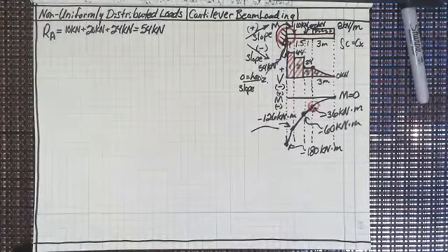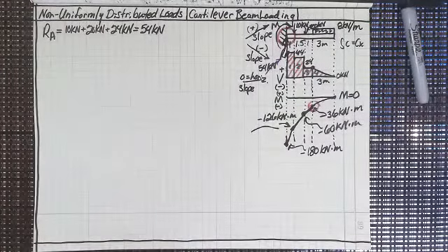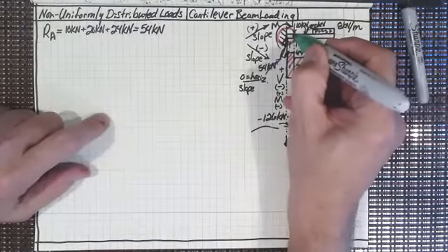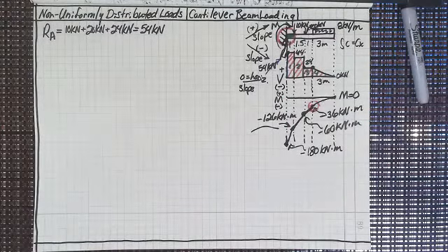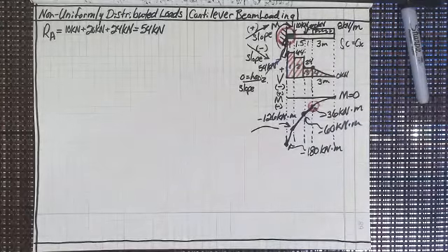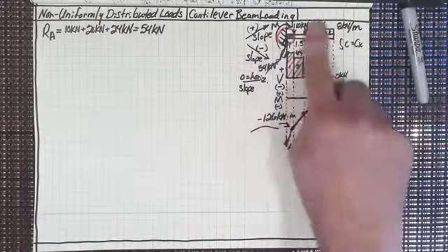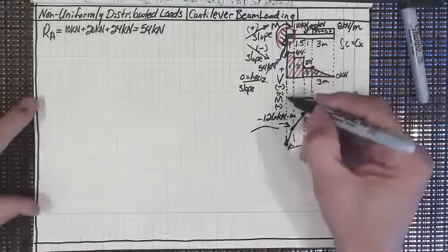Where is the most torque being placed? It's being placed right there where it's hitched into the wall or whatever. And where, let me get the green pen, is the greatest shear stress? The greatest shear stress is right here within that first thing too. So that's where we really have to worry about a cantilever beam breaking or whatever, right at where it's attached to the wall, right? We're jumping up and down on this, it's a diving board, whatever. But that's what we have.